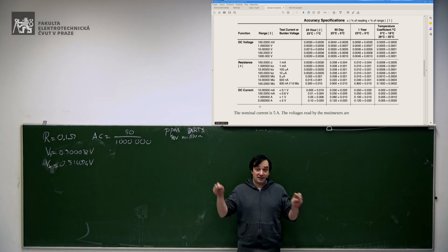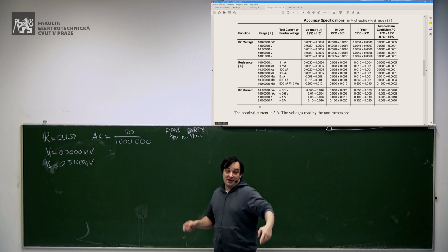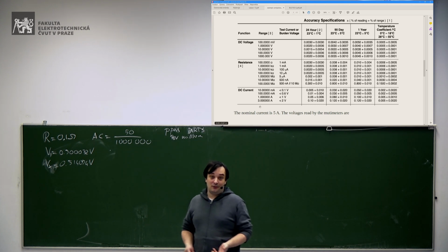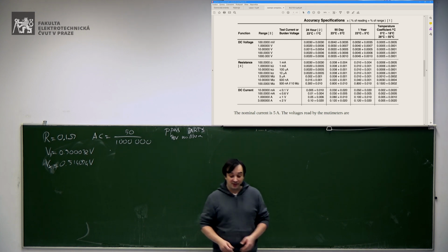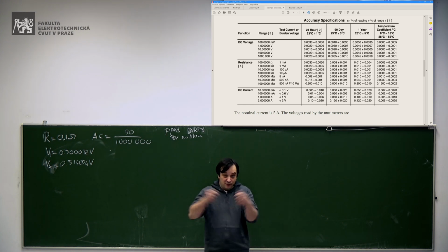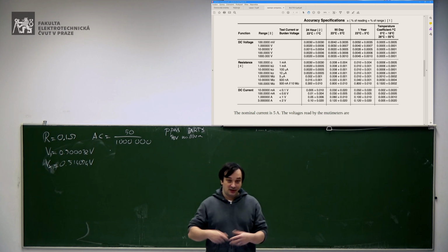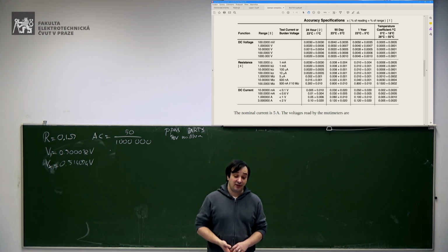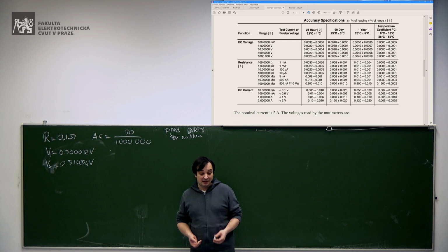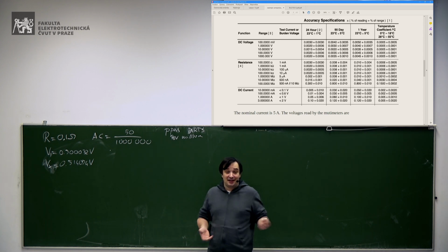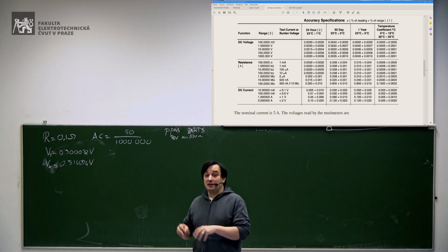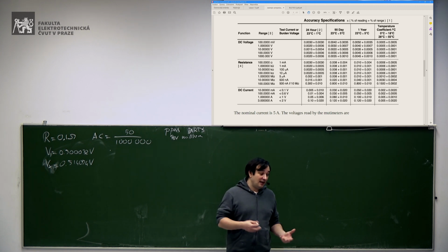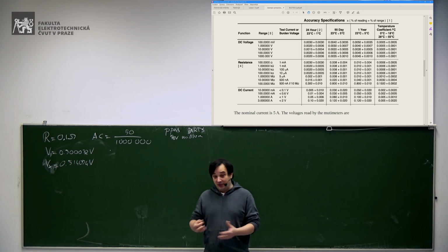This system with 2 multimeters and a very expensive standard, when I can use directly the resistance mode of this multimeter. I use the 4 wires method, as you know, to reduce the effect of the resistance of the cable, and I can use directly this measurement of resistance of the multimeter. So why should I complicate my life? Well, today we make some calculation and we find out what happens if you use one method or the other.